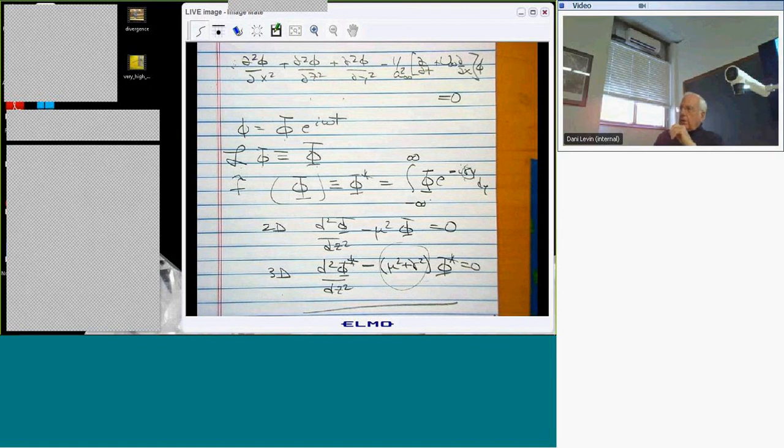We're moving at less than the speed of sound, so the flow is being disturbed before we get there, right? So we're going to need to take a Fourier transform with respect to both x and y. But it will formally lead to the same kind of solution in transform space. But then when you do the inversion, because the Mach number is less than 1, the inverted integral has a different and much more complex form for subsonic flow.